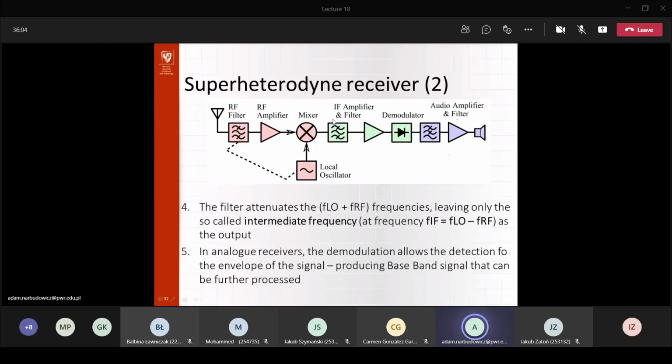And why intermediate frequency? And why actually a selective filter and not yet a low pass filter? This is exactly the whole concept, or the key, of the heterodyne receiver. It turns out it's much more practicable to have a mixer which does not convert our signal directly into baseband, but uses some intermediate frequency before it is finally demodulated to the desired baseband.